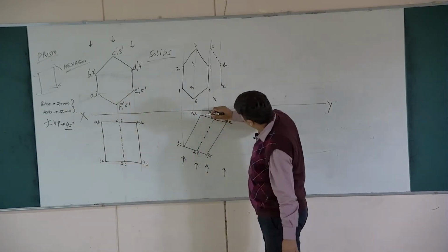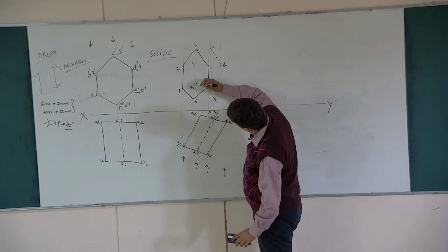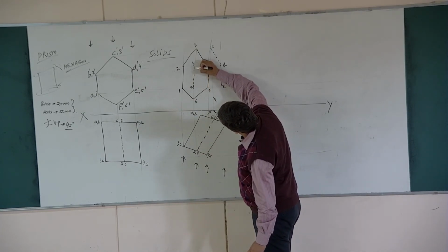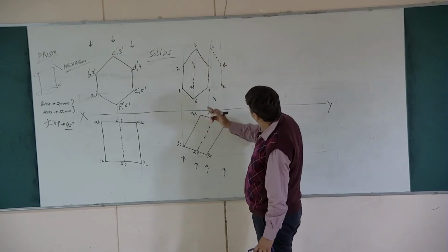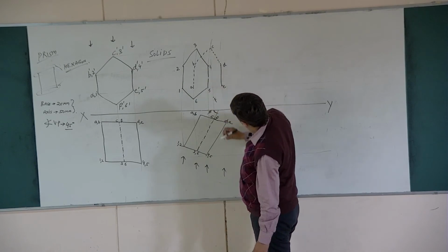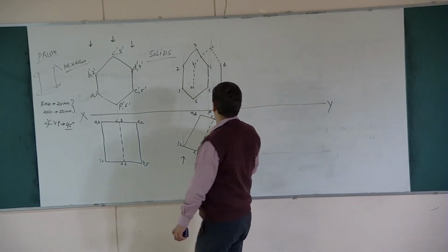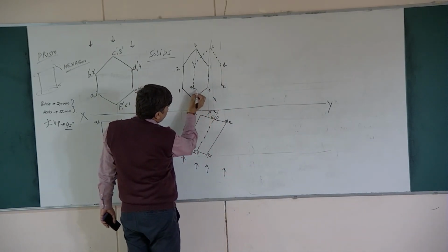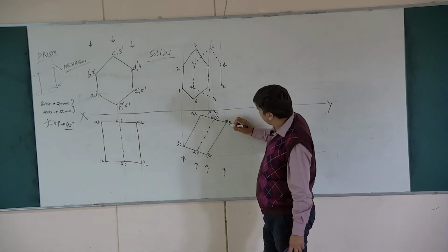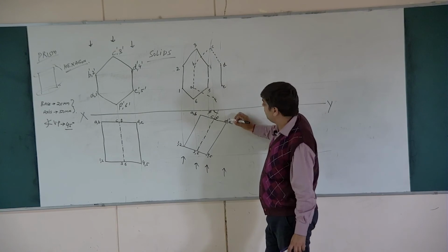Similarly, E to F or A to B, let us say first of all A to B. Whether A to B is clearly visible? No, it is not visible. So it will be hidden, dash dash dash dash. B to C, hidden. A to F, hidden. E to F, since E is continuous, whatever is connected to E will always be continuous.